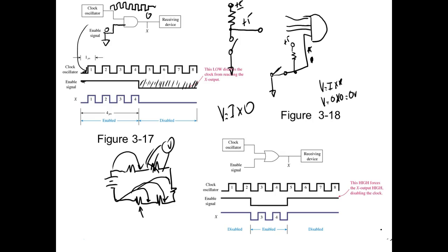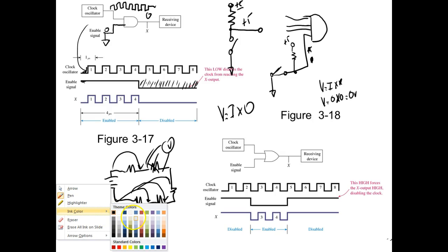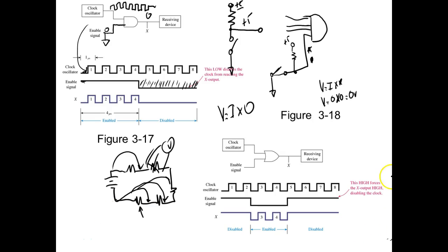So when it goes back to saying that whenever you do have current flow through, you usually have to drop 0.7 volts. No, that's a diode. A diode is not a switch. A diode is a semiconductor. Semiconductors will always drop a voltage. That's a big difference. So even a transistor, I'm going to use transistors like a switch. A transistor will drop a voltage when it's turned wide open because it's not a switch, it's a semiconductor. If it was a switch, then it would drop 0 volts. So if I measure 0 volts across a transistor, it either means it's shorted, it's bad, or the power's not applied to the circuit.